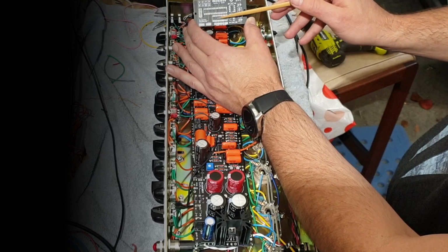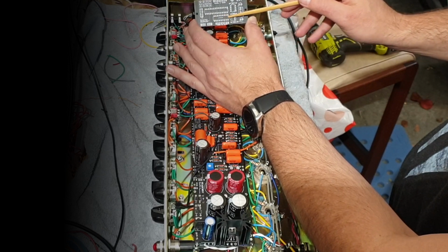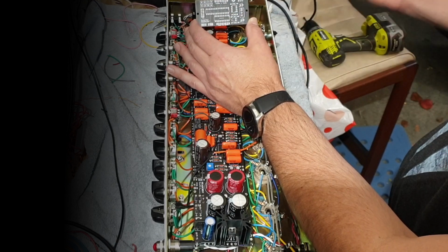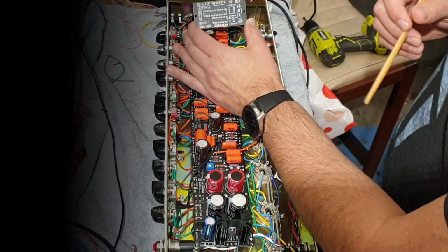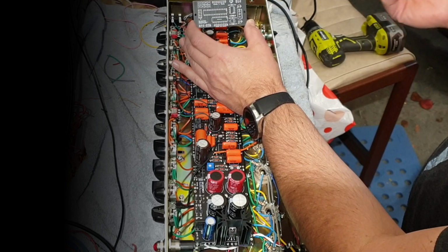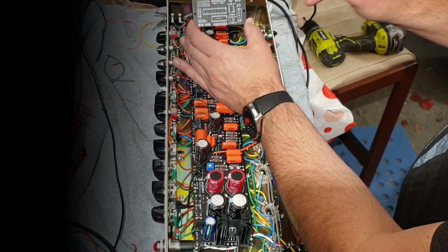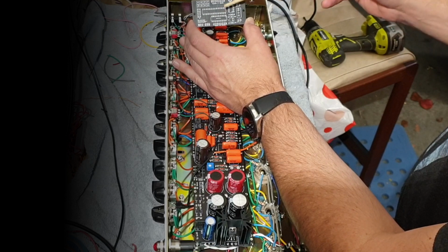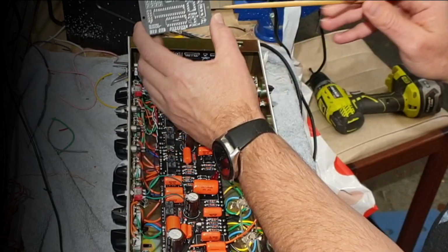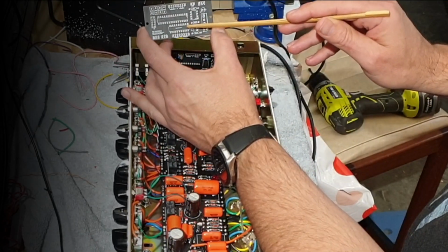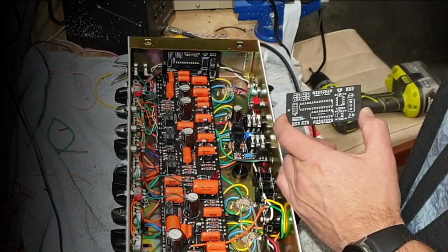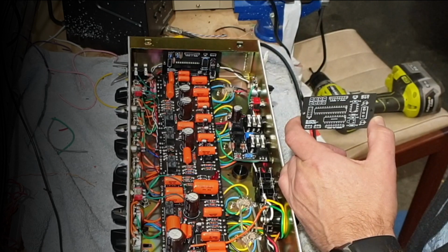Okay, so this is the thing. This is the chip that's actually doing the business to drive the relay coils, you know, set them to ground and let them activate back and forward. Now, there is a small issue that you need to be aware of and work around when you're dealing with a 5-volt logic circuit and 12-volt relays. If the NPN array chip is operating at 5 volts, it won't drive the relays properly. It won't allow them to activate off and on.